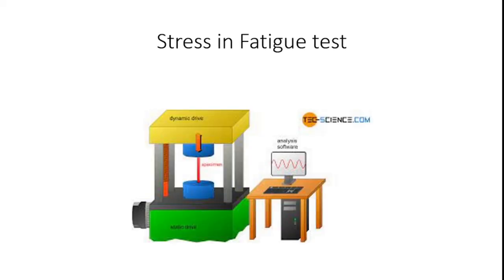And also in fatigue, a lot of stresses act on the specimens. What stresses act on the specimen during fatigue loading? The stress in a fatigue test usually is cycled between a maximum tensile stress and a minimum tensile stress, or between a maximum tensile stress and a maximum compression stress. Compression stress is always considered a negative stress.